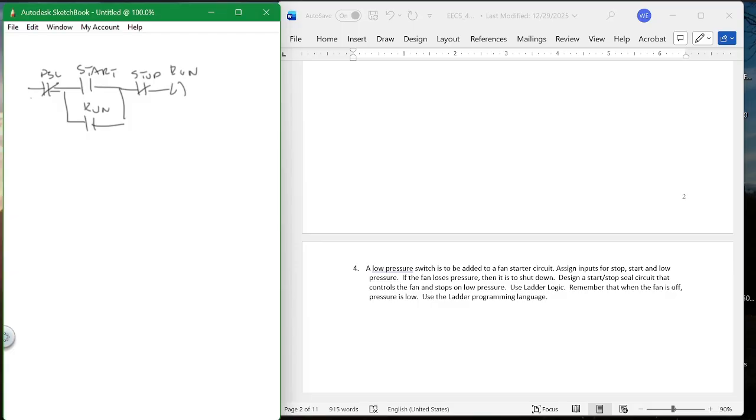So you have to add a timer on here that does this basically, timer 1 done. And when it's done, it opens up. In other words, it's on until the timer is done, and you put the timer over here. Or this can be done a number of ways. I'll say that. This is not the sacred way of doing this. You can do it a number of ways. Here's my timer.